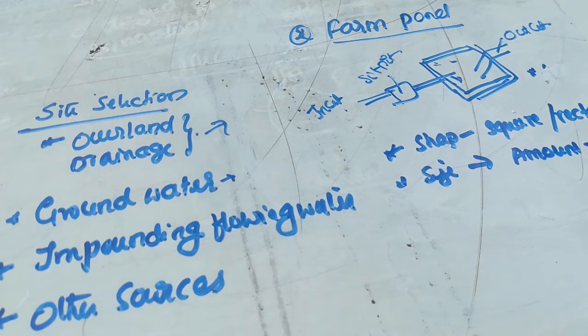However, impounding flowing water can have adverse effects. It can block fish passage, warm the water downstream, add excess nutrients to your pond, and cause sediment from upstream to fill your pond. The latter will require occasional removal. Heavy flows can also be difficult to contain. Generally, more problems are encountered with this type of pond and they are not recommended to be built in this way. Sometimes it will disturb the ecosystem, so that is maybe not suggestible for some reasons.